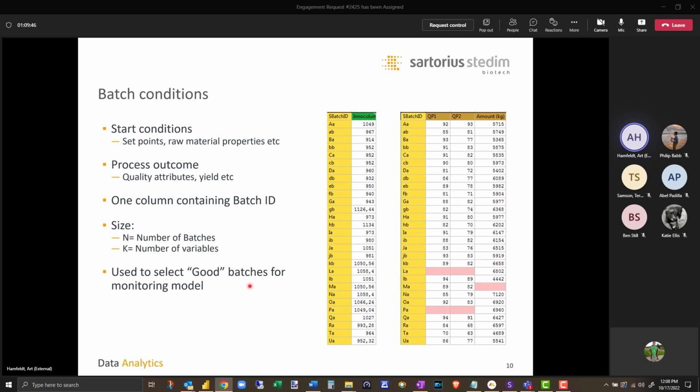We want to have a very, very narrow distribution of batches. And if we want to predict, we want to have reasonable and maybe some slight outliers to what you normally would like to operate under, because we need to have the ability to predict through the normal operational space. So if you're predicting, you can't use just this normal operational space to predict itself. You need a little bit more data outside of it to make sure you've captured that space accurately and you've captured enough variation through that predictive space.